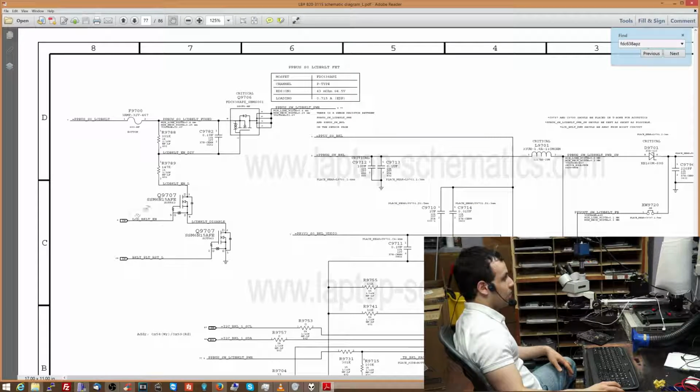However, if the LCD backlight enable signal goes to this transistor, this is an N-channel MOSFET. The way this works is when it sees power, it opens and allows power to go through. So once this opens, it's going to allow this power to go through over here, and you're going to have this going to ground. So when that 3 volts shows up over here, that 3 volts is going to cause this to turn into a wire, which is going to send this to ground, which is going to activate this voltage divider. Remember, a voltage divider needs to go to ground in order to actually work.